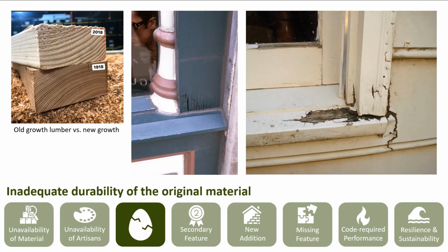The image in the middle shows a wood storefront where a piece of replacement wood frame is rotting at the base, likely from a lack of paint on the end grain before the board was installed. The surrounding historic wood elements outside of the red box remain in good condition. The image on the right shows advanced wood decay at a window frame and surrounding elements.